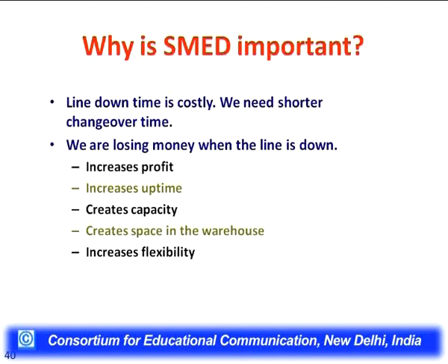Increases flexibility, as we have already discussed, because we are now taking the least time in changeovers, we have become more flexible, our machines are more flexible, and these machines can be set to any requirement of the customers without wasting time on changeovers and setups, because we are now using the SMED concept. Reduces cost per unit. When there is no idle time, more efficiency is there in the system, and the per unit cost will get reduced.